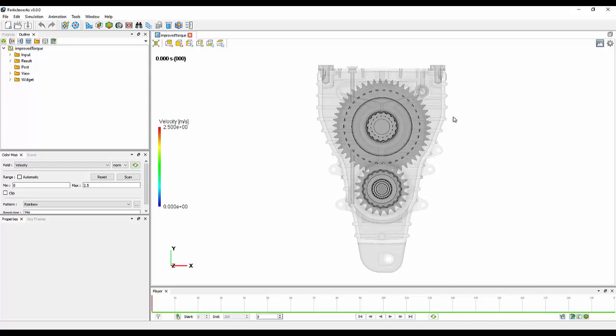So the way that the improved torque model works instead is it applies a potential amplifier to the surface tension coefficient of any particle which is in contact with a fast-moving polygon. The effect of that amplification is scaled by how fast the polygon is turning. So for a much slower gear, it would feel a much lower amplification than compared to a faster moving gear.